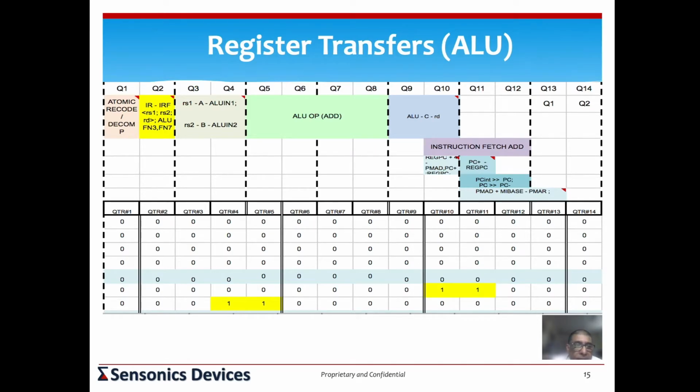And along with that, in parallel, we also do the decompression of 16-bit instructions. So if you've got a 32-bit instruction fetch, then you might choose to put 2 such 16-bit decompression engines, because both of them can do it in parallel. And at the end of that first quarter, if it's an atomic instruction, you'll have 3 instructions sitting there, the bit codes of the 3 instructions, 32 into 3.